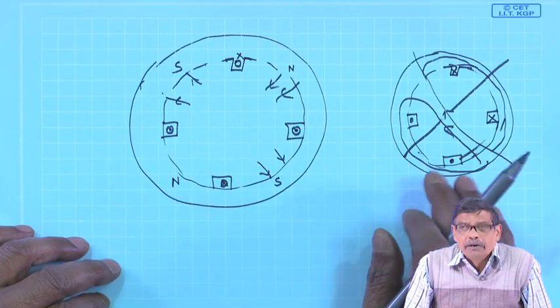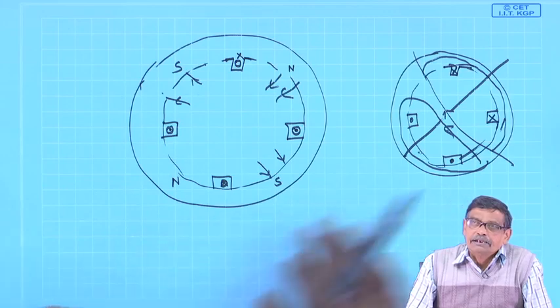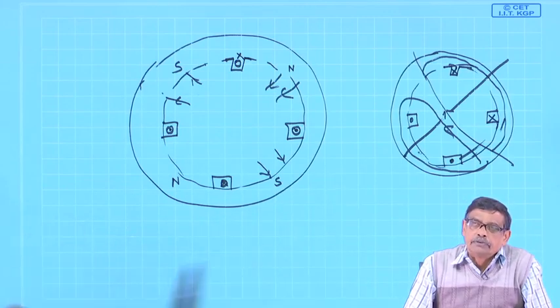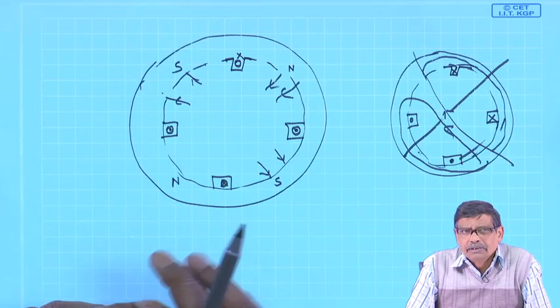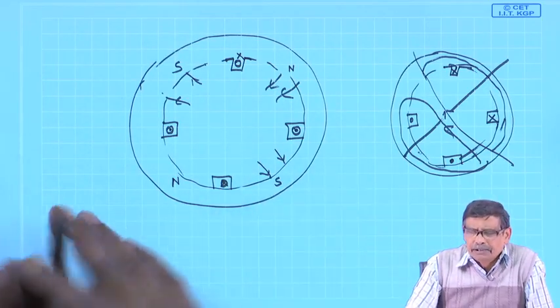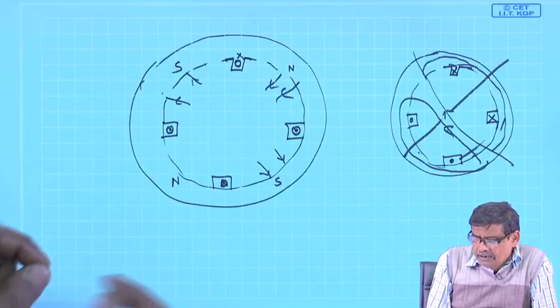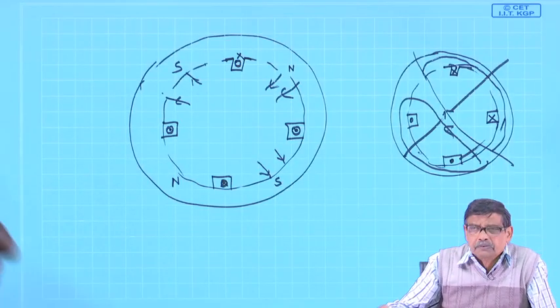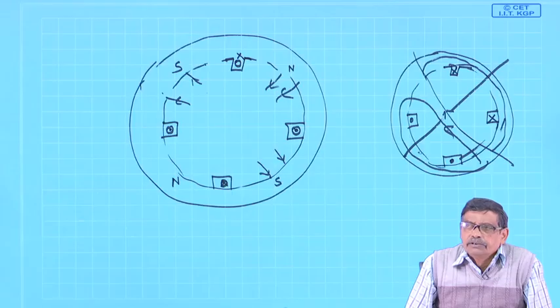We will not go much into this, because in earlier days these were very nice methods proposed after a lot of research work. You have one 3 phase winding, but some terminals should be available to the users. By interconnecting those group phases, you can generate 2 poles in the ratio of 1:2.